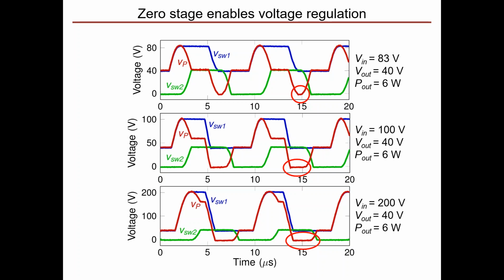Is this intuitive? Is it an intuitive guess that it is an order higher? It's based on a fundamental calculation. What I will say is interesting here is that for the inductor, for example, we can pull all of the energy it stores out every single cycle. Whereas with the piezo, because it has such a high Q, we can only pull part of the energy out every cycle. We can't pull it all out. So it becomes a question of how much energy we can pull out and what's reasonable. And so we actually prefer to focus on power density rather than energy density for these specific applications for that reason.